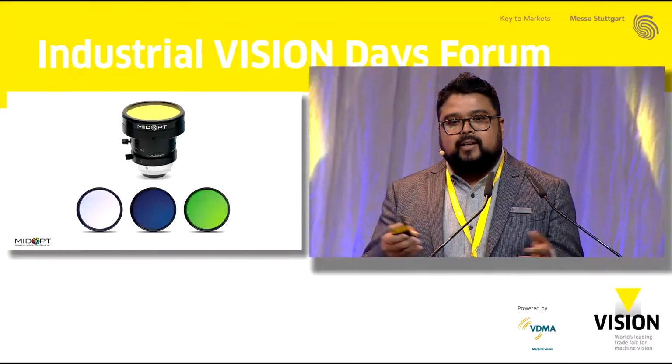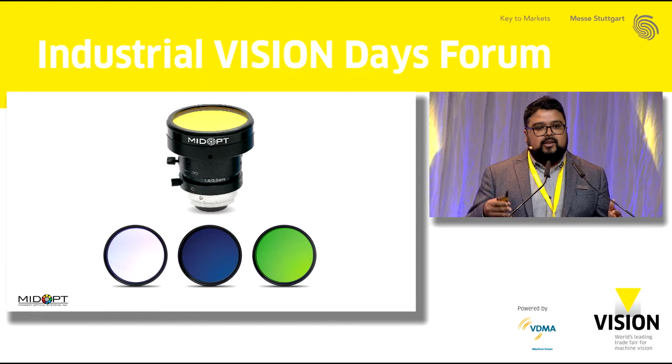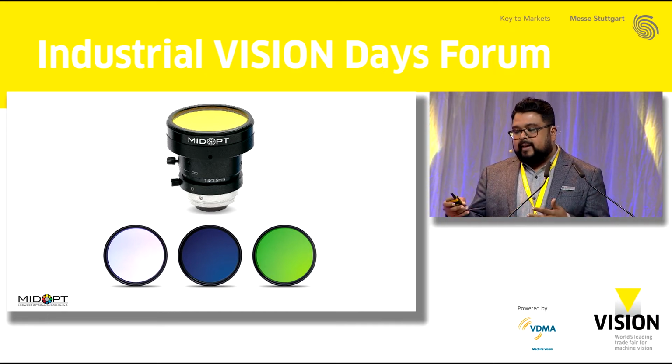My colleague from Edmund alluded to optical filters, but I want to impress upon you more how important they are when you're designing and deploying a machine vision system. What's a filter? A filter is simply an optical component that goes on at the end of your lens, or sometimes before your lens, in front of your camera sensor. It's going to control what wavelengths are entering your vision system and which wavelengths are being blocked.